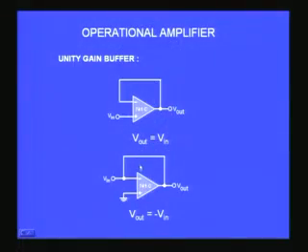You can also have a small variation of the circuit, where the input is given to the inverting input and the other input is grounded. So here you get output minus V in. In the previous circuit, V output is plus V in. So that one is a non-inverting buffer, this is an inverting buffer. The two different circuits are both very useful. They provide you a buffer.